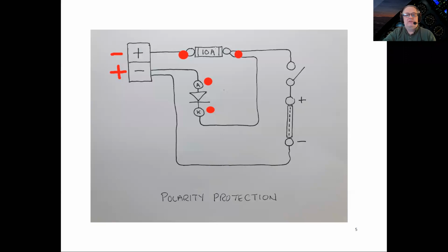And so what we would have is this fuse would be taken out of the circuit as soon as they connected their supply. So the current never gets a chance to flow through the other line, through this line here. Potential would have come up to here, but no current flow because the switch was open. And so when would the fuse blow? Literally as soon as they connected the battery into the circuit, it would blow the fuse.